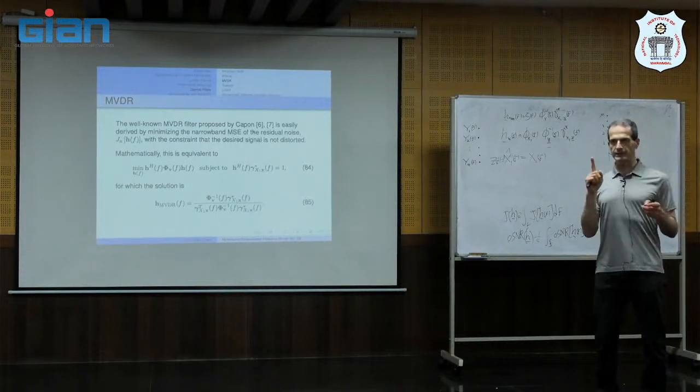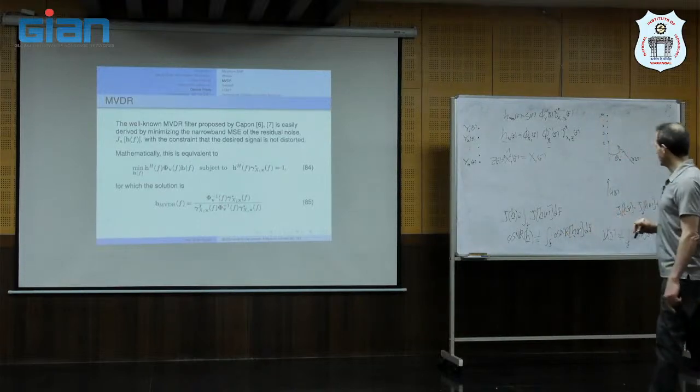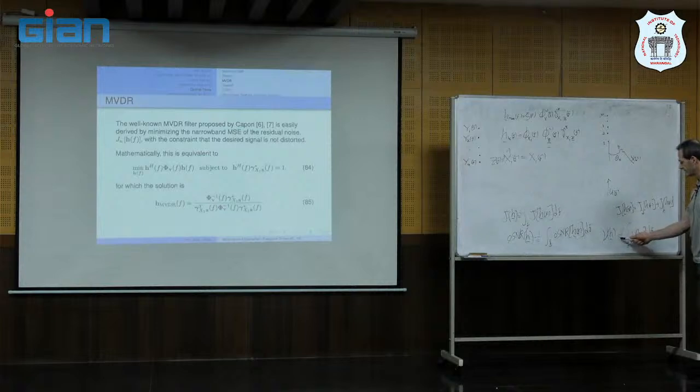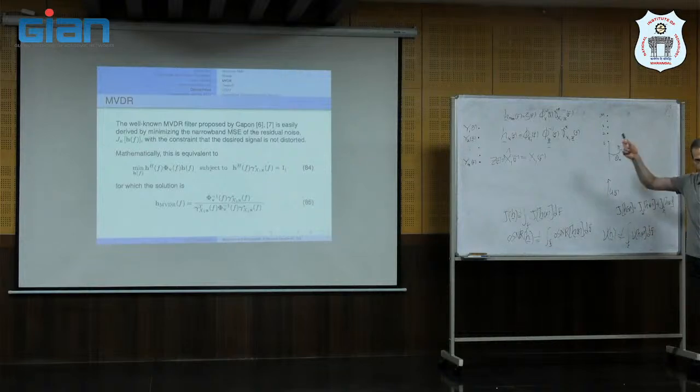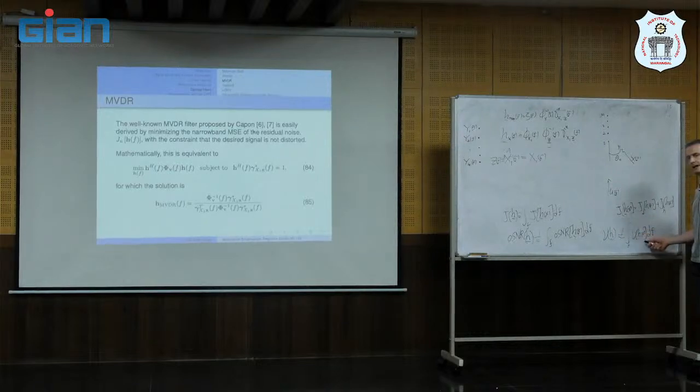Okay, so in the broadband, you see, the weight that I need to multiply each distortion is weighted by the variance of the desired signal in that frequency. Okay, I can go back to the expression. But here I have certain weights, which means that signal components which are strong, in those frequencies, I need to minimize more the distortion.